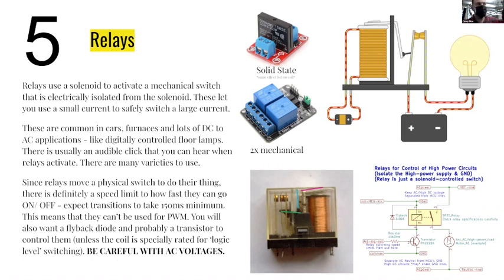In order to try and maintain its magnetic field, because really it wants its amount of magnetic field to stay constant, it will induce a voltage in itself as it's fizzling out. It's a weird quirk of how electric charges move, but you get a backwards voltage that these flyback diodes are letting dissipate instead of going back into your Arduino. And so I'll try and explain that a little bit more with a video. It's electromotive force, which is another word for voltage, because we need 15 words for it, apparently.